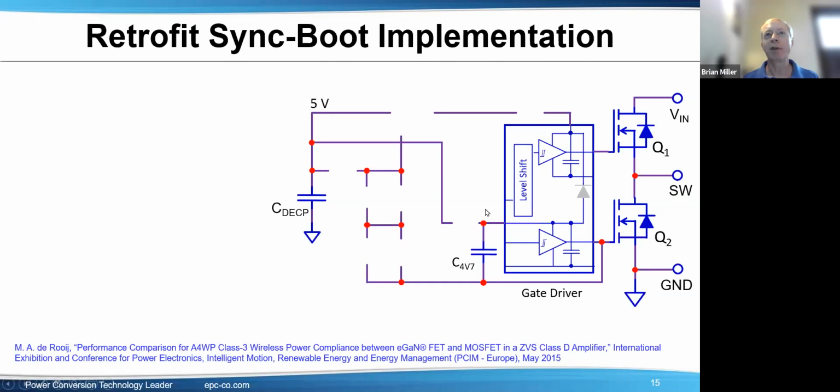Here's the start of a retrofit. I'm going to fill in these blanks, don't worry about that, of how to do the sync boot implementation for high-speed circuits. Here's the power FETs once again. Here's the gate driver. In many of the EPC boards, you'll see the TI LM5113, which has now been upgraded by TI to the LMG1205. So that's a typical one we use in some of our boards. And you'll see in gray the internal diode that we're trying to eliminate the function of, to keep that from being turned on.